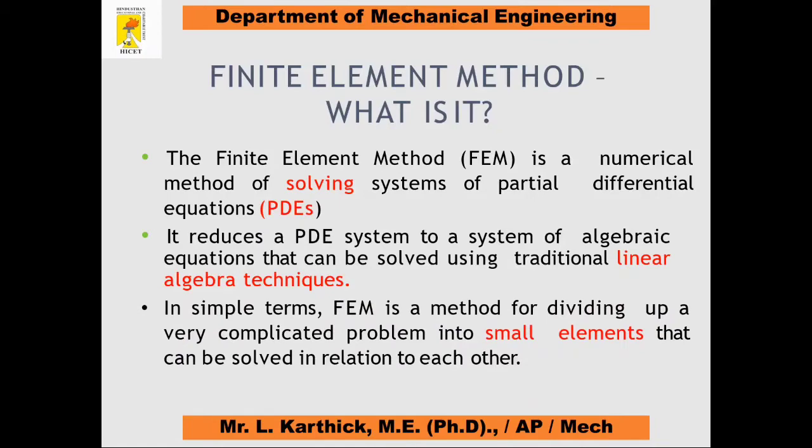In simple terms, the finite element method is a method for dividing very complicated problems into small elements that can be solved in relation to each other. This process of dividing a complicated problem into small elements is called discretization. So what is meant by discretization? Whatever the structure may be, we split it into a number of smaller elements and then apply the force on each element to find the displacement, stress, strain and other values.